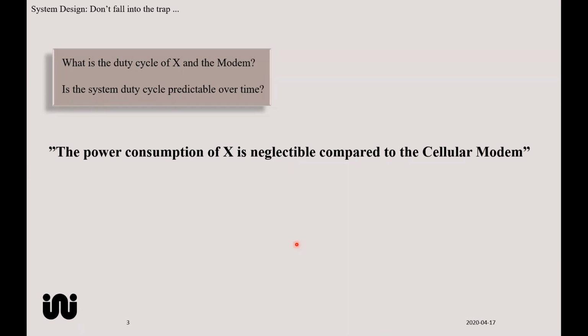And the second bullet I would like to raise is that you don't have to consider duty cycle only at the start of the design, because you also need to take into consideration if you do a firmware update of the sensor in an IT system, for example. If you update the firmware one year from now, would you still continue to keep the duty cycle of the system? Or is there a risk that someone else comes in and breaks that duty cycle rule? That needs to be covered already in advance so that you never break this.